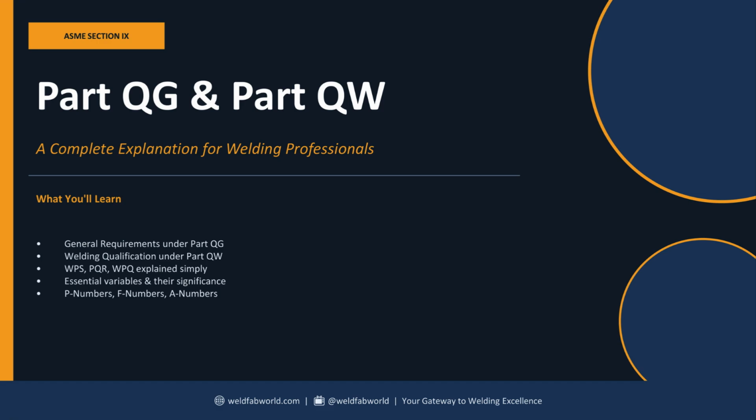Let's get into it. Today's video is focused on two specific parts of ASME Section IX. Part QG, which covers general requirements, and Part QW, which covers welding. There's also a Part QB for brazing, but we're not touching that today. We're sticking to welding. Here's what we're covering: the general rules in QG, then the three key documents in QW, WPS, PQR, and WPQ, then essential variables, and the P, F, and A numbering system.